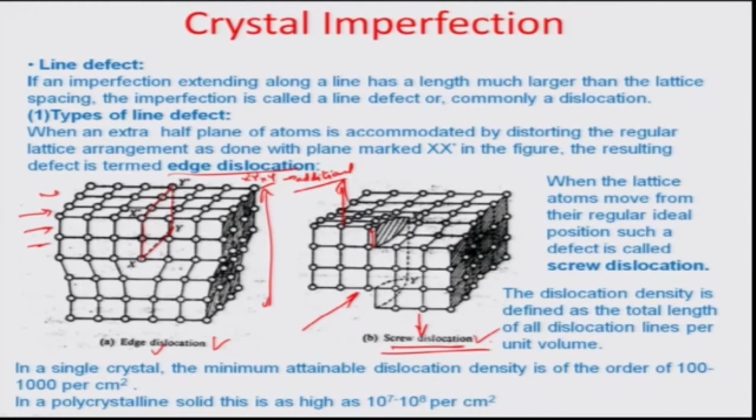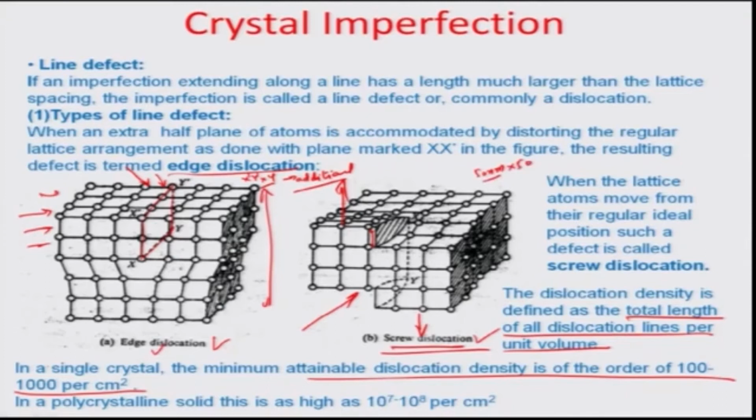Okay. So, the dislocation density is a very important term here. You can say that it is the total length of all dislocation lines per unit volume. So, in this particular case, let us say I had 50 nanometer line defects, about 50 of them, in about 1 centimeter cube of the material. You can think of what this dislocation density would be. So, you have about 2500 nanometers, 10 to the power of -9, per centimeter cube, which makes it 10 to the power of -6 meter cube, and 100 centimeter makes a meter.